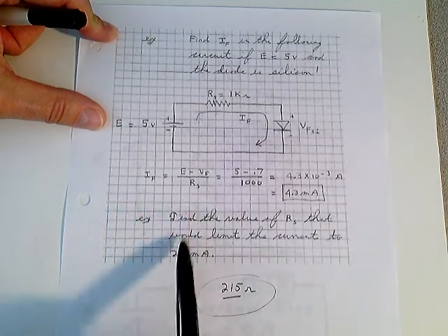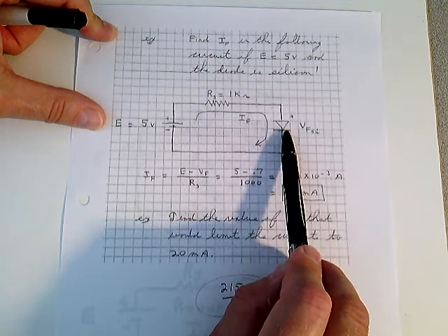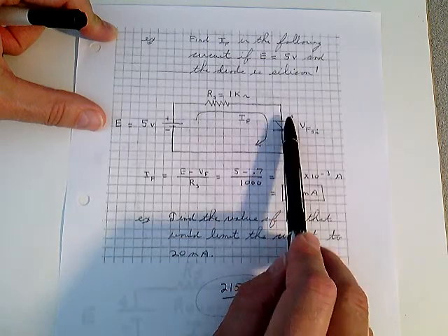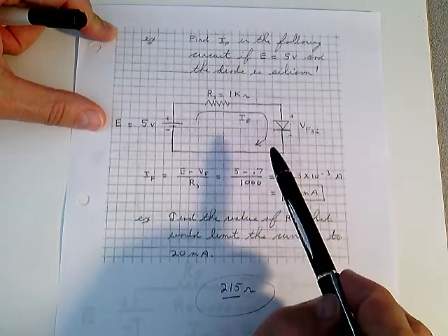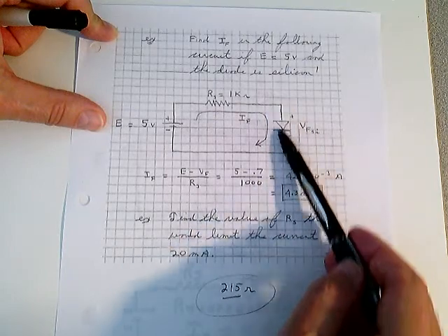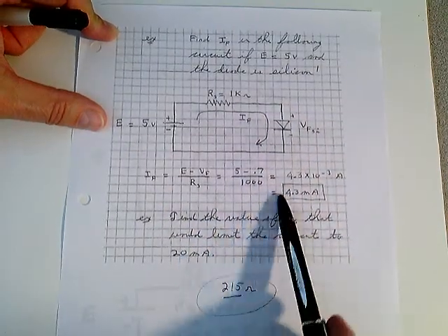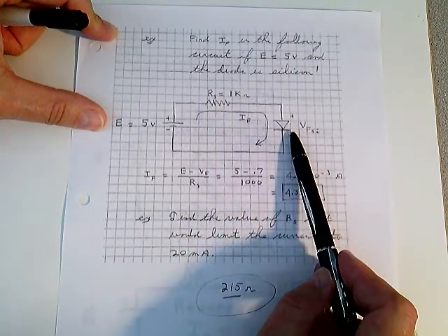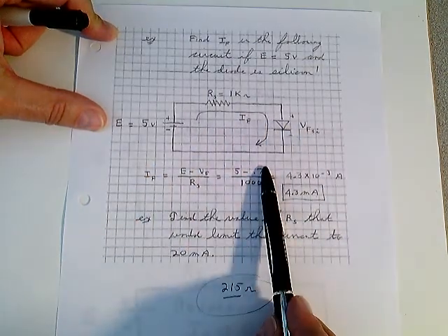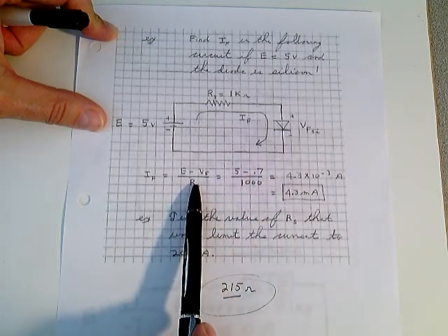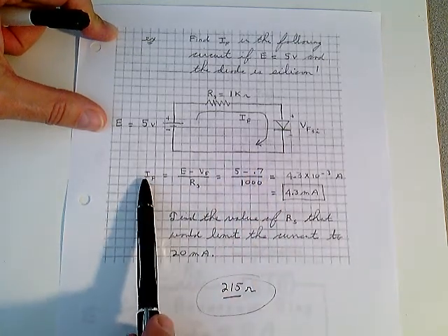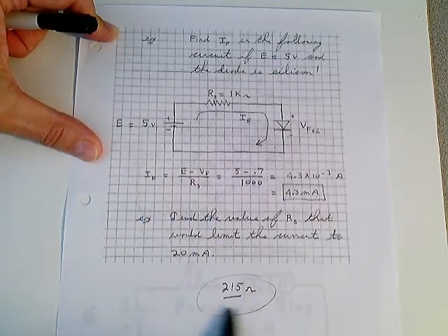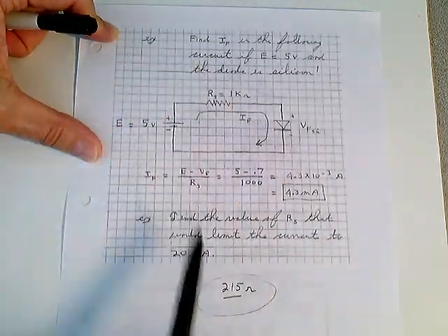The reason we're going to do this is because this diode is going to be a light emitting diode for us coming up in some labs. It's going to be an LED. So when it's forward biased, it emits light. And the typical current through an LED is 20 milliamps. So I want you to calculate what resistance value this would be if you're going to drive an LED. It's a design problem. I want you to use this equation, and you're going to have a value of RS this time, and you're going to have a value of IF this time. You're going to solve for RS. I want you to work it out and see if you get 215 ohms. That's the answer. Make sure you know how to do both of these problems.